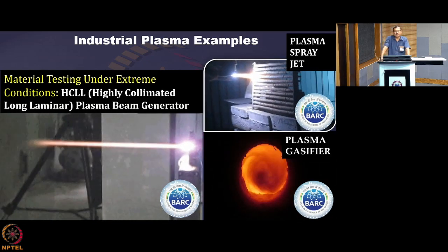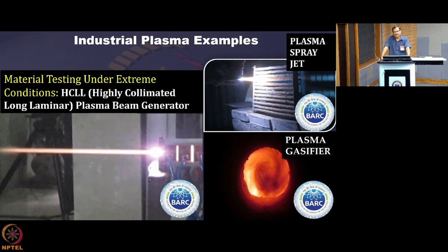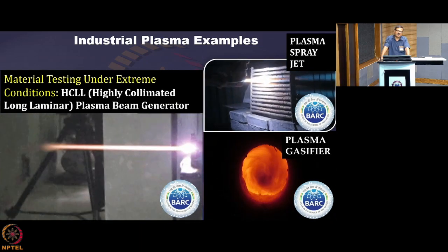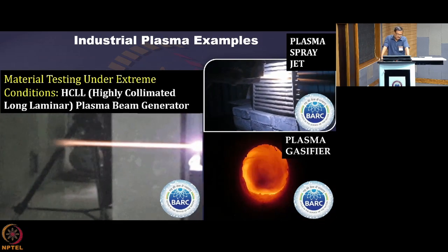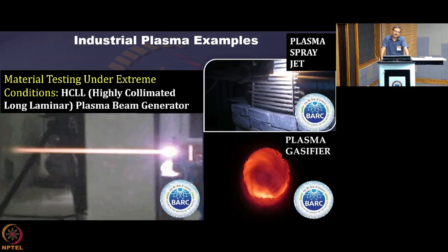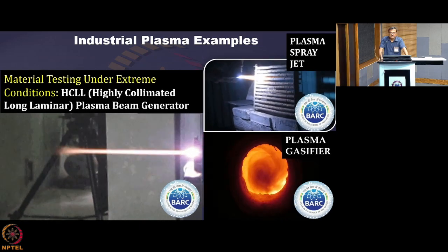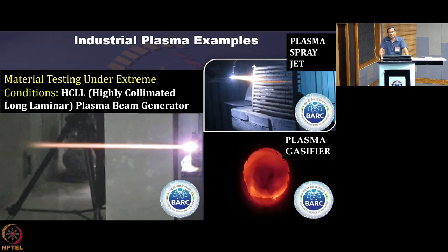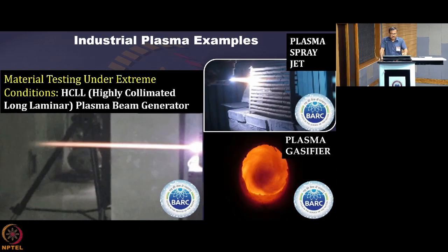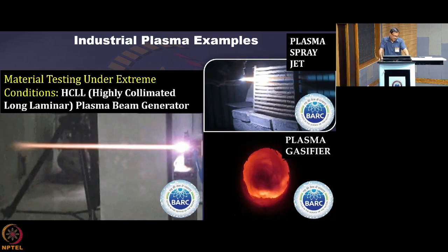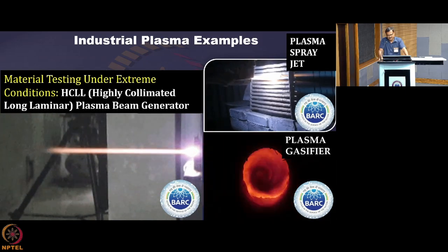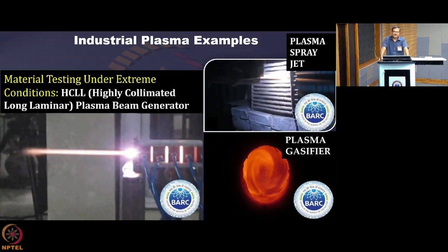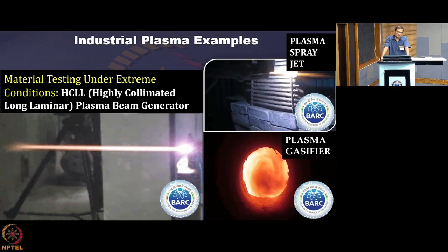When you burn at a temperature in the presence of oxygen, say around 400 to 600 degrees centigrade, that is the temperature that you achieve when you burn these materials in the open atmosphere. Now the problem is that some of the isomers of dioxin and furan are carcinogenic at the nanogram level.